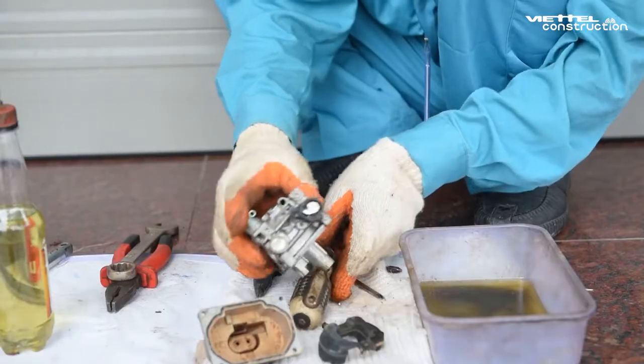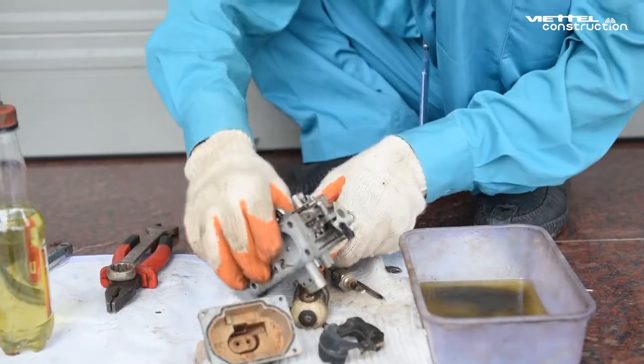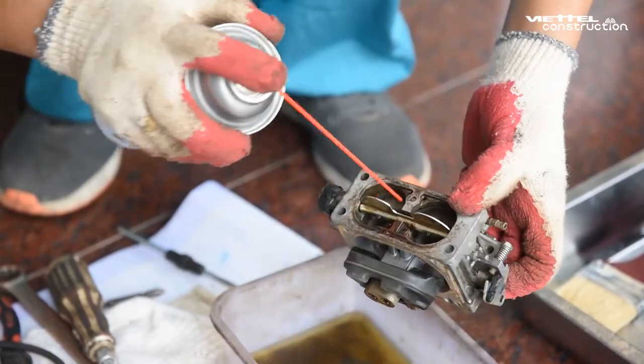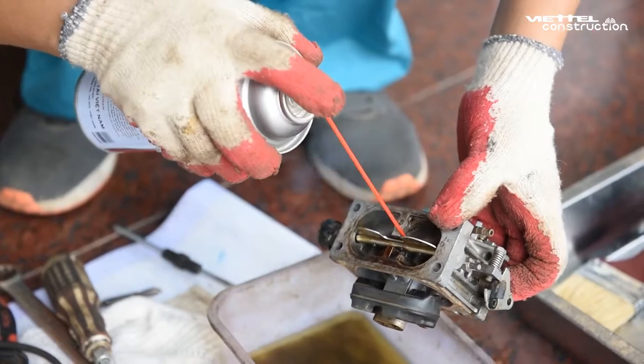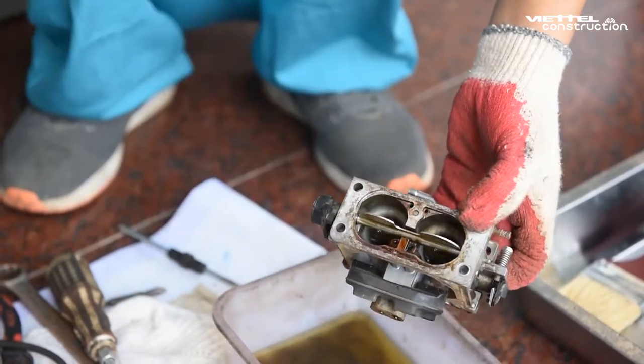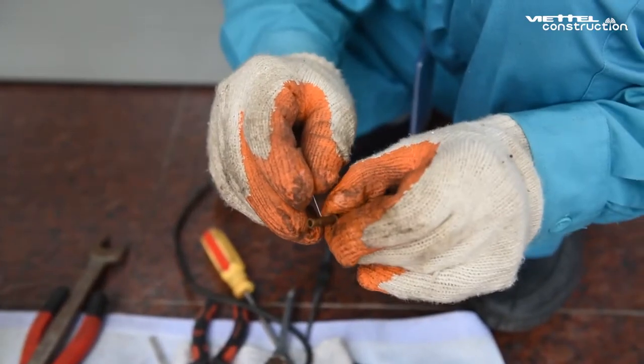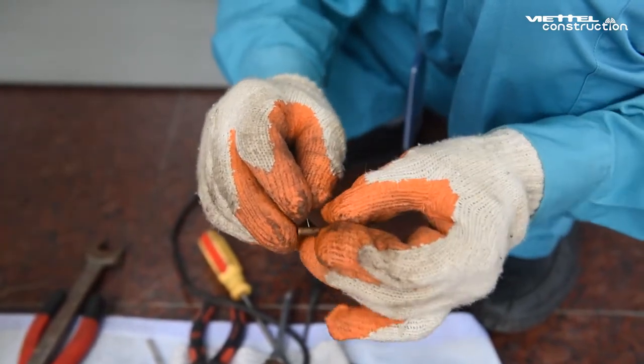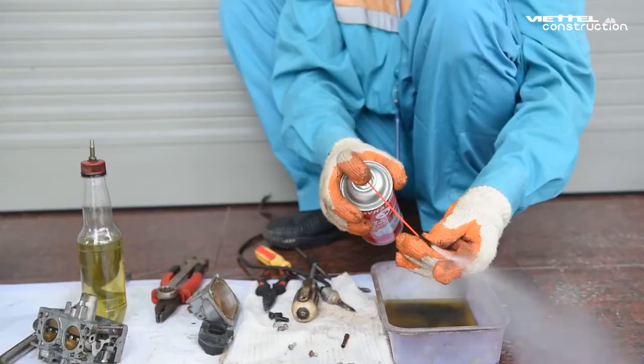Check the cleaning of carburetor, air filter, and calibration check of the exhaust, inlet valve system, clean solenoid, main jet, nozzle, air inlet and gasoline lines inside the carburetor. Note: when cleaning, it is necessary to avoid damaging, tearing or deforming the seals, gasket in the carburetor.